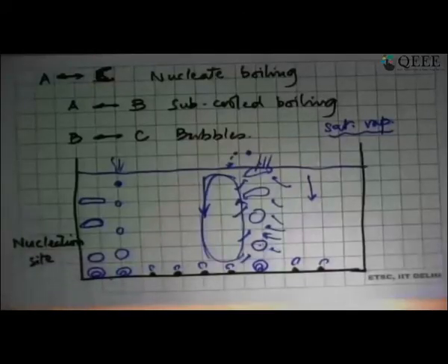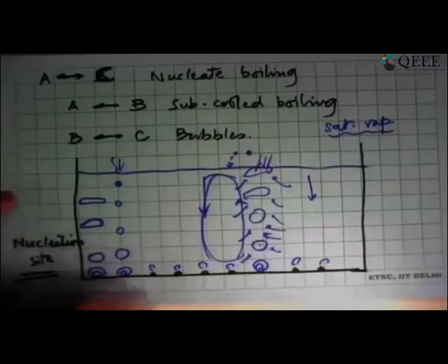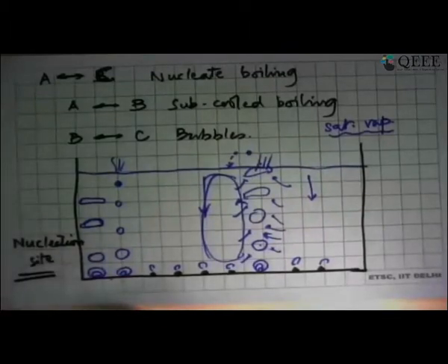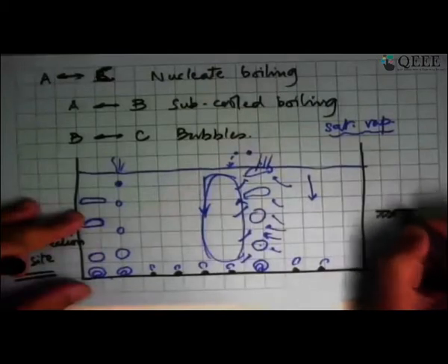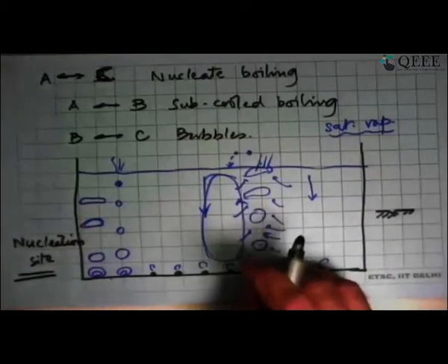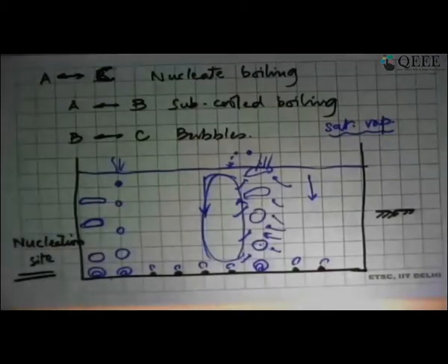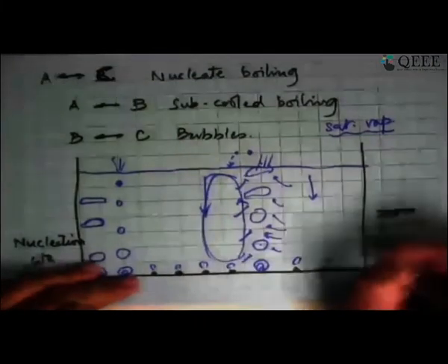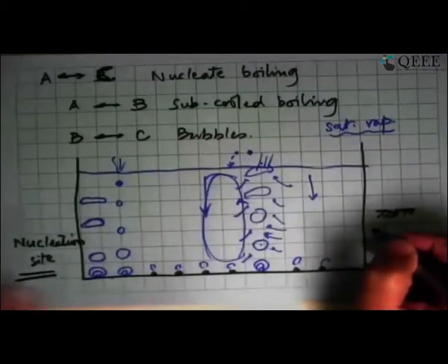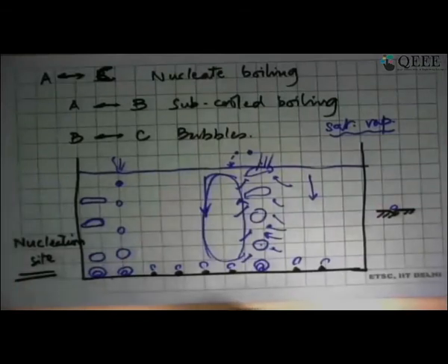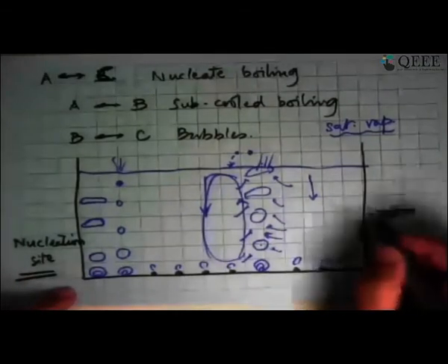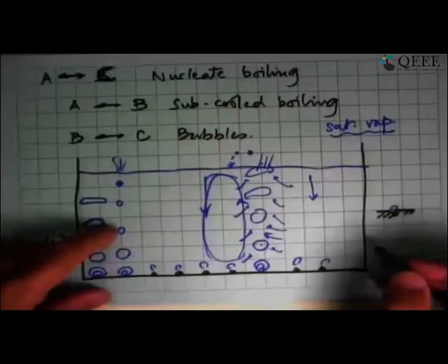What is happening is that for boiling or phase change to take place, this surface needs what is called a nucleation site. This could be a micro roughness on the surface, a small protrusion, or a little cavity in the surface, and that cavity could have any shape, it doesn't matter. What this cavity does is that locally you have a very large heat flux, and that is where nucleation and the bubble formation begins. And that's why the nature of the surface is so critical to where the boiling will take place.